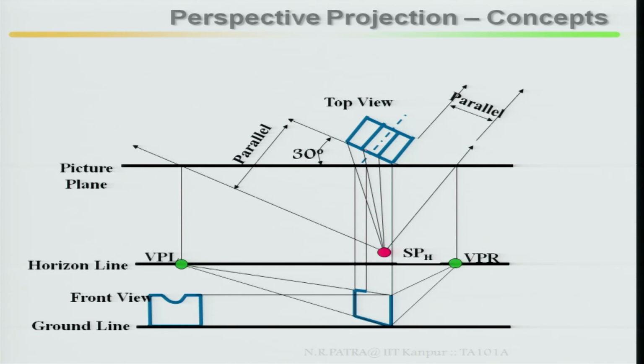So then the inner face you mark it, then draw it, then plot your semicircle, taking into consideration this is your diameter. Identify your center line, draw your arc, then go to your right side face, the right side edge, mark it along this right face, then draw it, then mark it, then draw it.